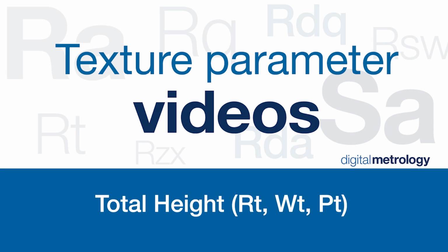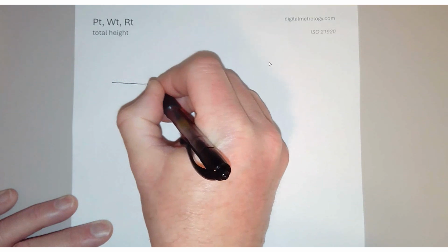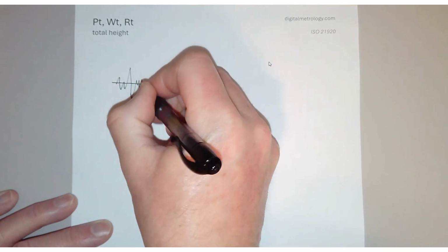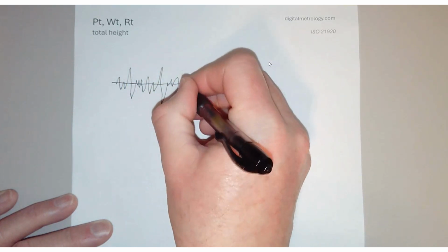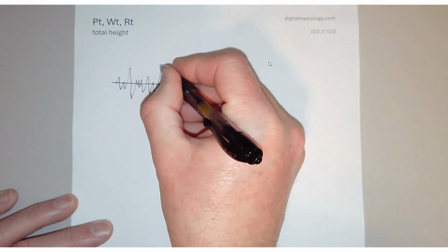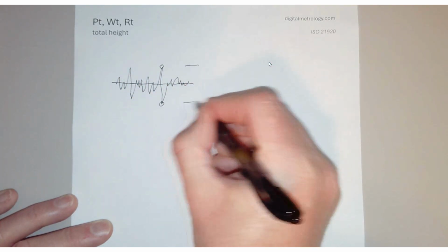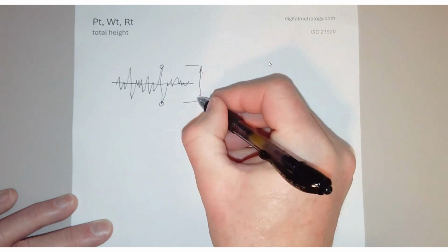The T, or total height parameter, is quite simple to think about. We have some data. It could be roughness, it could be waviness, it could be primary, and we're simply going to report the height of the highest peak relative to the deepest valley. That is the T, or total height of that surface.